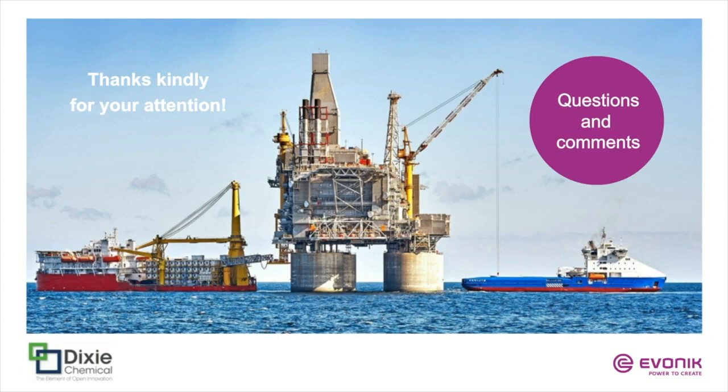So those are the two that are the most important. Those are the two that we've really been able to change and modify with the introduction of blends of dianhydrides and monoanhydrides. The density data, which is also important more from a processing and handling standpoint, is that the material is very lightweight, easy for fabricators to handle and use, and thermal conductivity, which we showed you also. We don't expect any great variance, but those, of course, are equally important properties for syntactic foam.